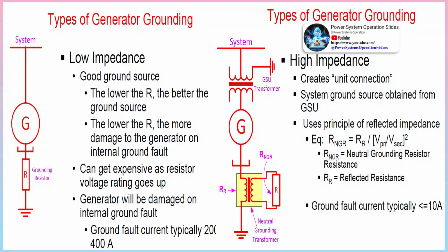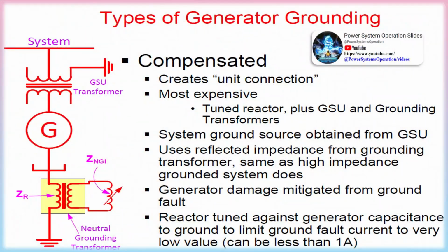Some of these protective arrangements are of non-trip type, i.e. they only generate an alarm during abnormalities. But the other protective schemes ultimately operate the master tripping relay of the generator. It should be noted that no protective relay can prevent a fault; it only indicates and minimizes the duration of the fault to prevent high temperature rise in the generator, otherwise there may be permanent damage in it.